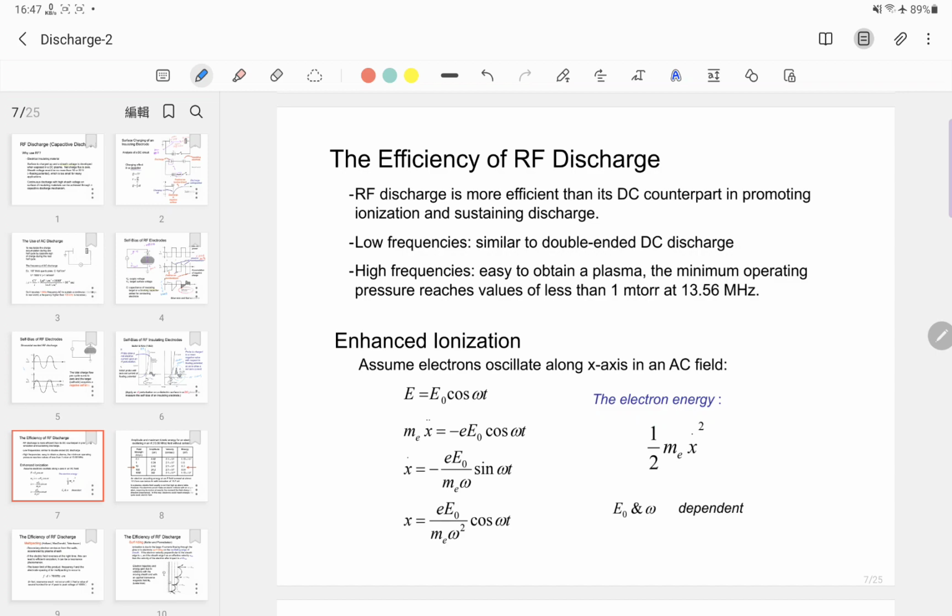Okay. And the frequency of RF power can be a few megahertz or less than a megahertz. So for example, for a low frequency RF power supply, the frequency is about 100 kilohertz. And for a high frequency RF power supply, the frequency could be 40 megahertz or a little bit higher. So there are different types of RF frequency people use for the RF power supply.